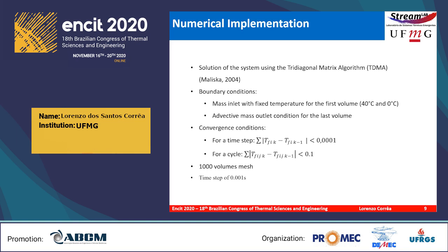2 boundary conditions were applied: mass inlet with fixed temperature for the first volume, and this temperature depends on whether it's a heating process or cooling process, being respectively 40 degrees and 0 degrees Celsius, and only advective mass outlet condition for the last volume.